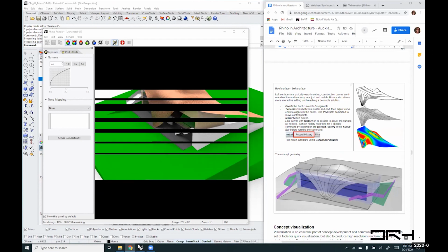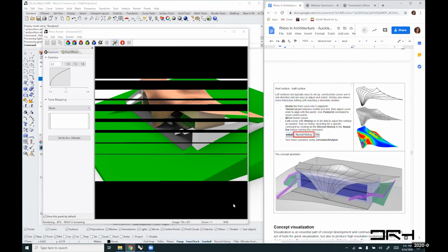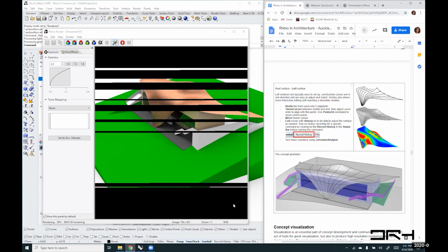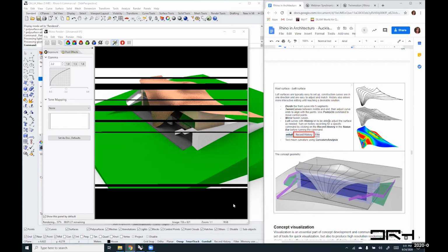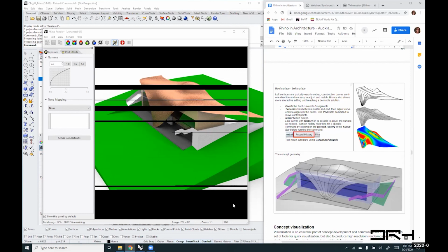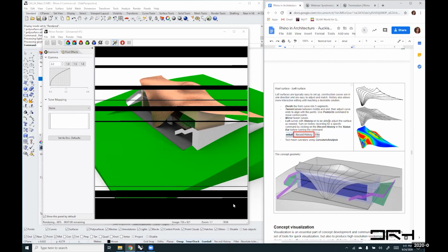You can also use the loft to control the direction of your ISO curves. So instead of, in our case, following the plane and a trimmed surface or patch, you can have a non-trimmed surface, which, again, gives you better control this way and a better curvature result, maybe creating strips on the roof to be able to panel it. So depending on your end goal, even the symmetry, you have better control over it using a loft.